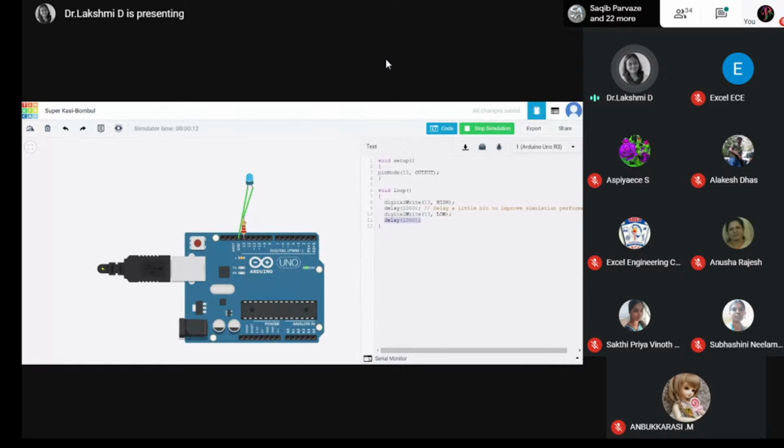The way you are going to imitate is to give the 13th pin for the output, then one pin for ground. That's it, very simple. I have not brought a breadboard either, only the Arduino kit, one resistor, and one LED. Just click and drop here, then give the wiring connections after bringing all the components. If you feel difficulty, use the delete button immediately. So for more clarity, I am bringing it to a different position, because earlier it was zigzag and you couldn't notice. So now it is showing.